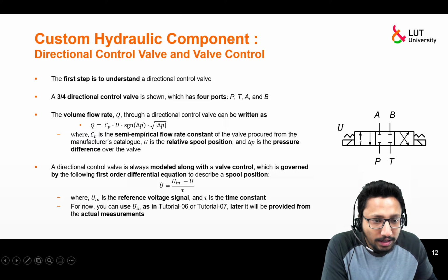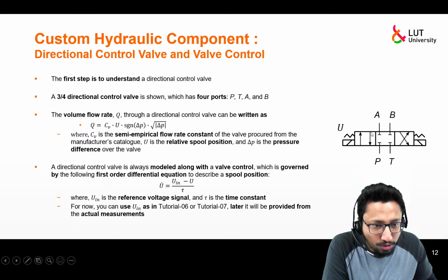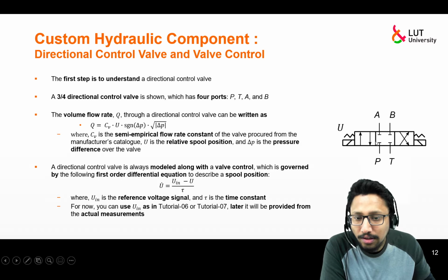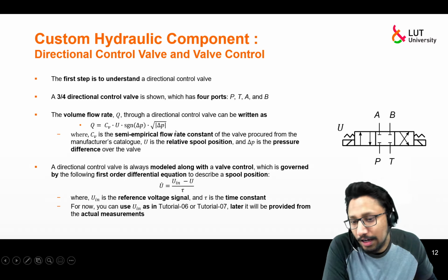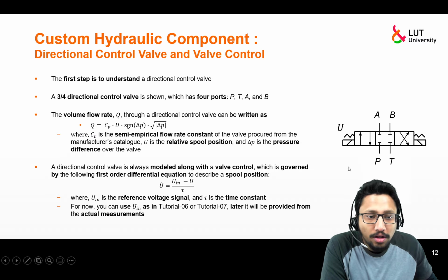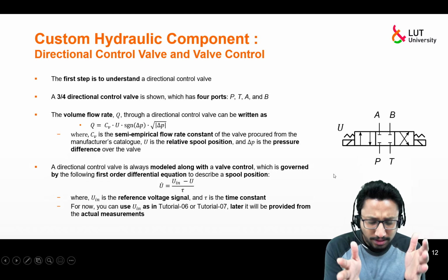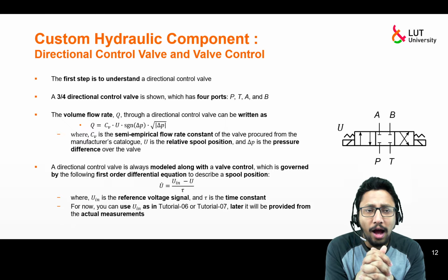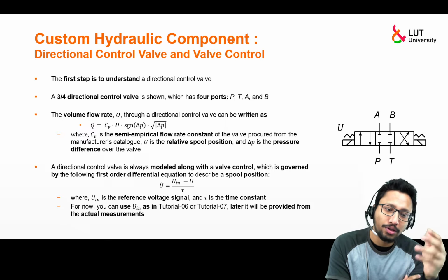So accordingly, we say let's this portion is U greater than 0 and this portion is U less than 0, and in the middle U is equal to 0. So basically the spool position, relative spool position. So first understand what is the functionality of this directional control valve, and then what are the governing equations.